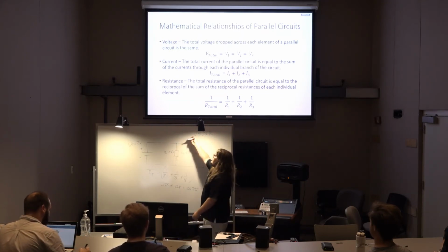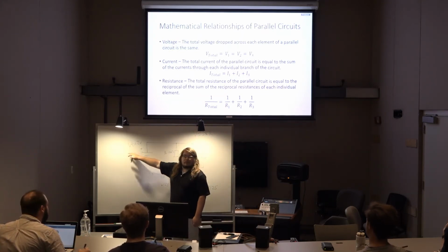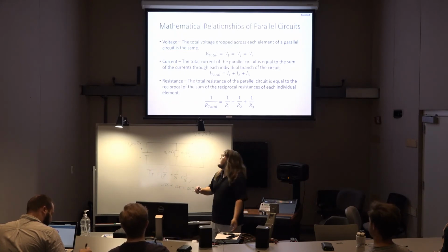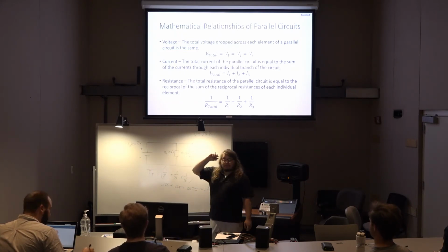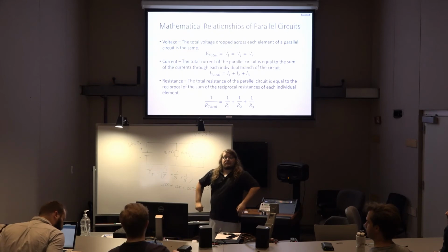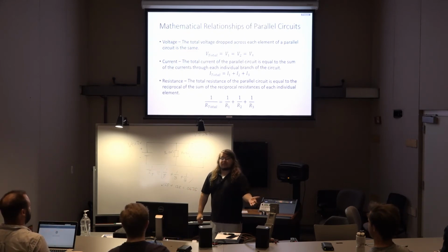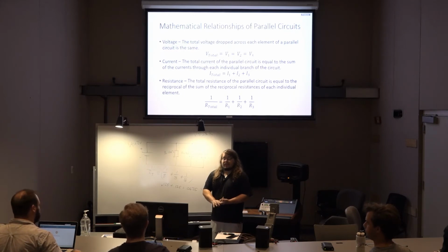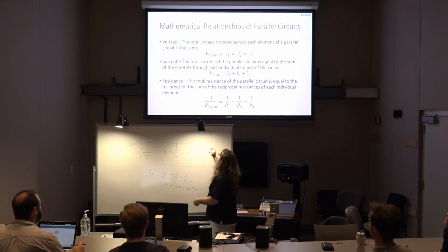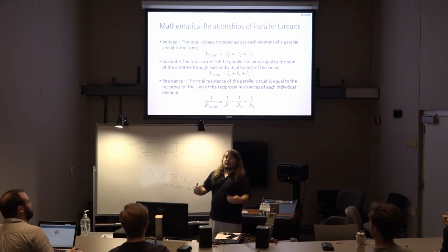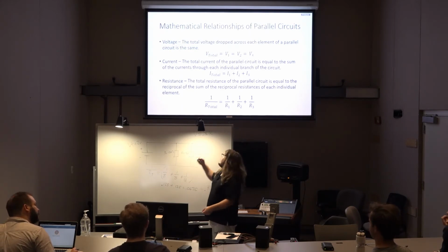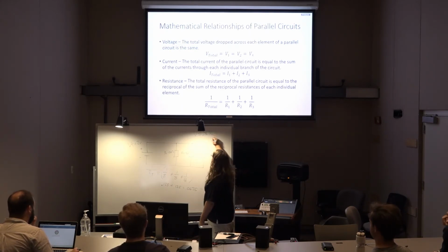We're saying that V stayed the same, the voltage source, as the last problem that we just did. What happened to the resistance? It went down. Last time we had how much resistance for the series circuit in total? 8 plus 8 plus 16, 32. So we had 32, now we have 3.2. So the resistance went down by a factor of what? 10.